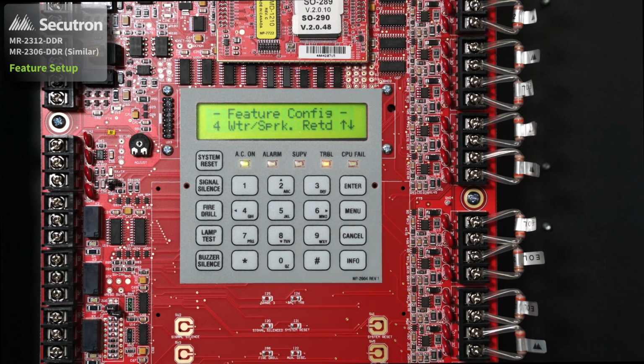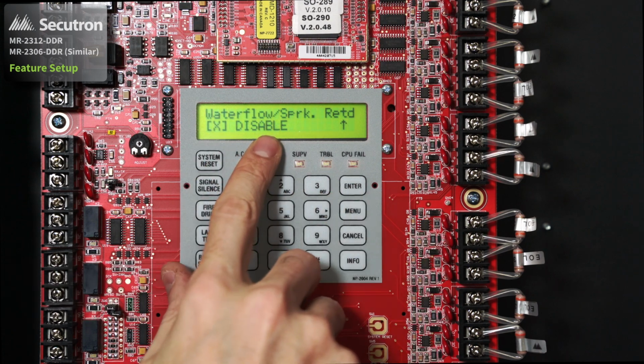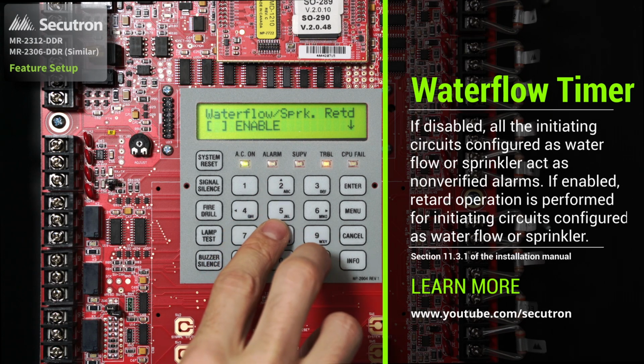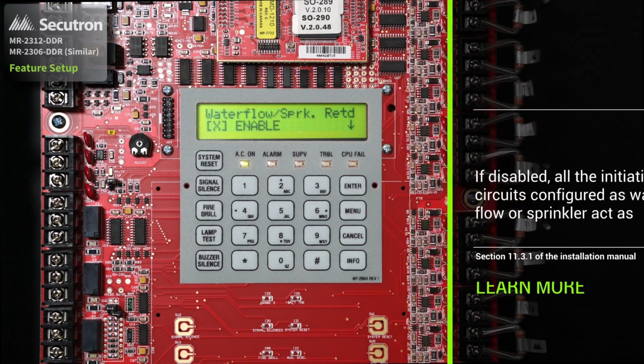The next feature is the water sprinkler retard timer. Now with this, if we select Enter, by default it has been disabled. If we'd like to enable that feature, we could press the up cursor and then the left or right arrow to apply the X. With the water retard, if disabled, all the initiating circuits configured as water flow or sprinkler act as non-verified alarms. If enabled, retard operation is performed on initiating circuits configured as water flow or sprinkler.